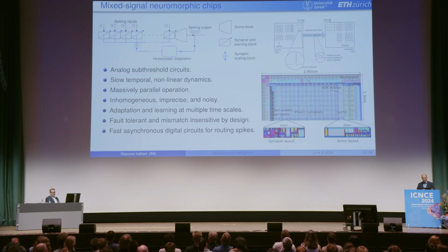So in weak inversion, using diffusion and Boltzmann statistics. We do try to slow down silicon. So the mobility in electronic transistors and the mobility in cells is very, very different. But we can slow down silicon so that we can have time constants that are in the same range of biological time constants. And people usually ask, why do you want to slow down silicon if you can go so fast? I will answer that in the next slide.